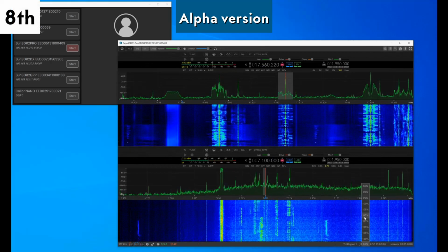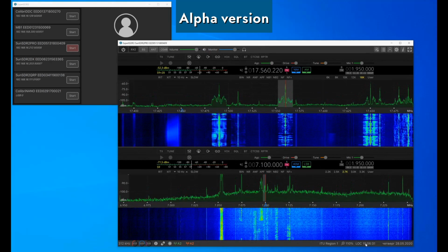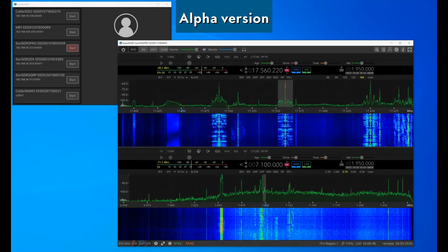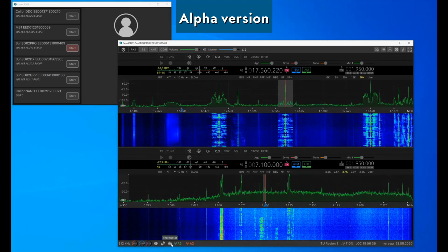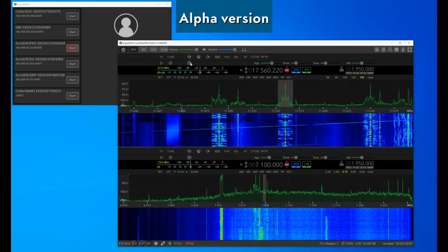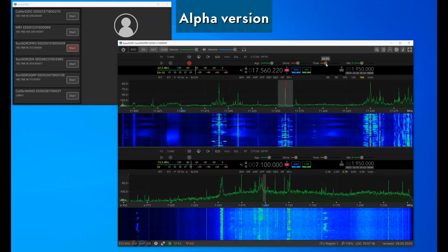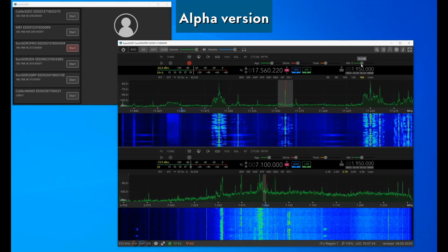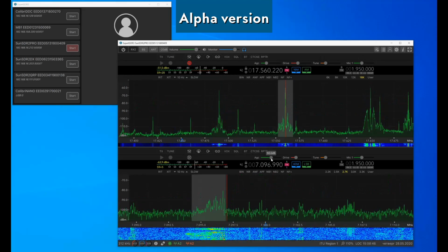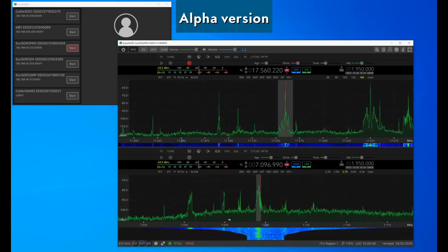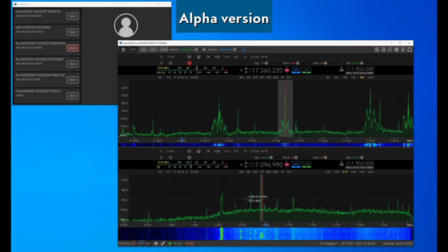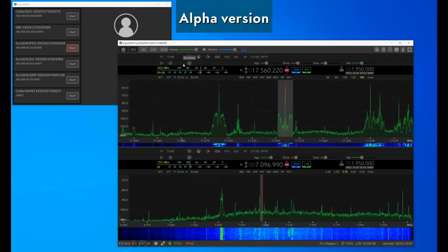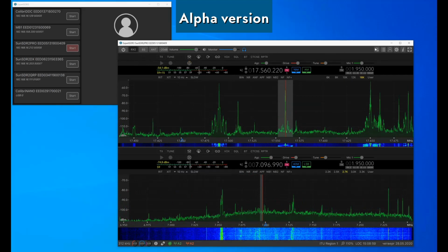Eighth, and last but not least, I should say that the ham radio world also has changed in the last 9 years. There are new popular digital modes like FT4, FT8, WSPR, etc. We'll implement digital modems in ExpertSDR3, so they are going to be an integral part of the software. These modems will share information with loggers via TCI. As you understand, it allows you to cut some third-party applications from your setup, which greatly simplifies it, leaving you more time to enjoy operation.